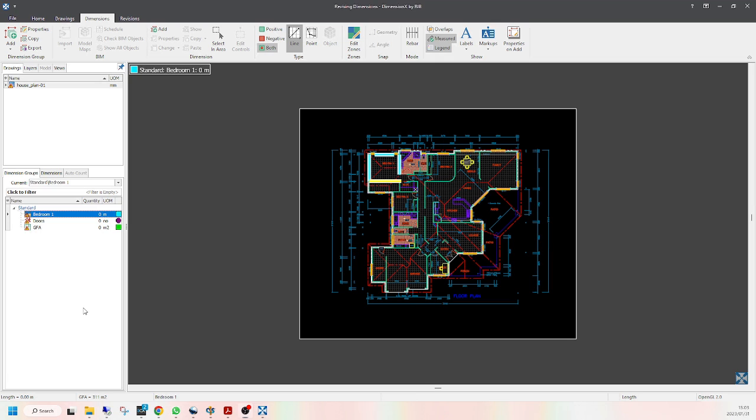DimX has a feature to help you identify suspect lines. These are invalid dimensions shown in yellow on your drawing. To find these lines, simply hold in the Control and Space keys on your keyboard, and DimX will take a line from your cursor to your suspect line to show you where they are. Then you can choose what to do with this line.